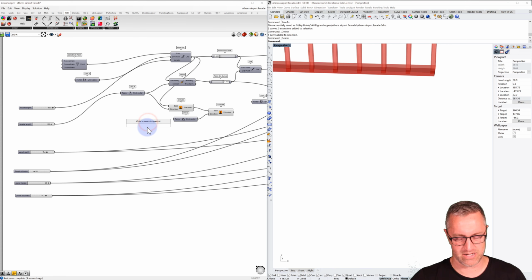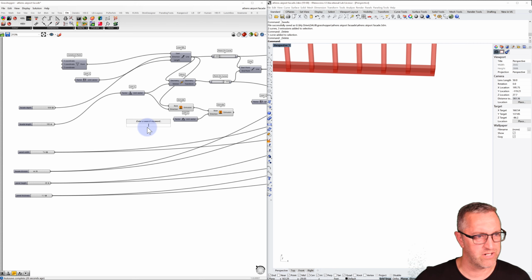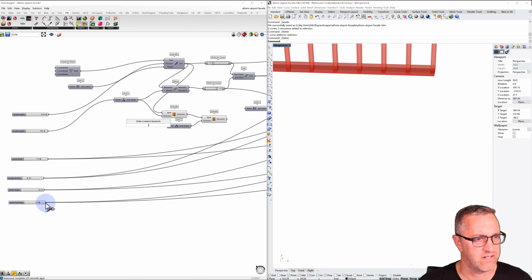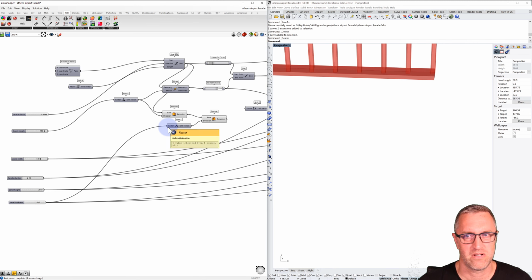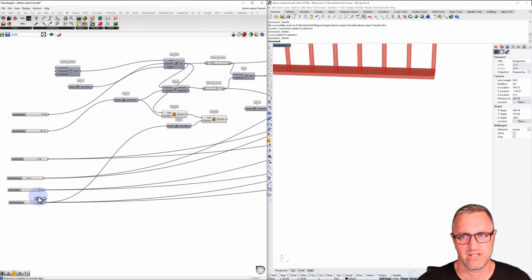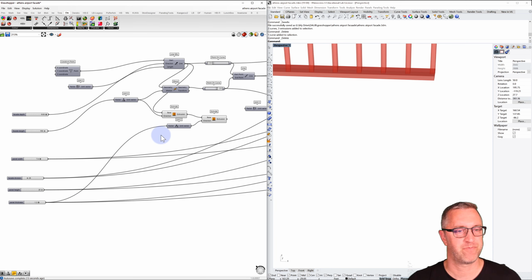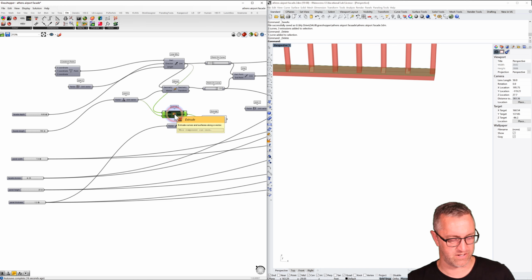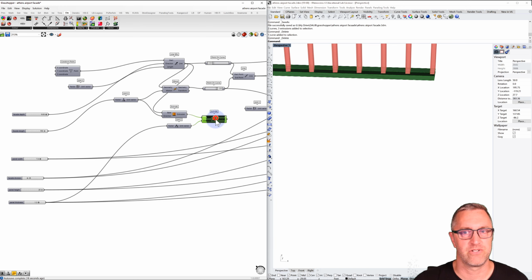So let's make a slider that also, we could use the panel thickness, which is a negative number, and then the thickness of the panel will match the thickness of that piece. That could be a nice thing. If you want those two things to be different, you could give it a different parameter, but I would use a negative number to do that. So let's hide our first extrusion. Now we have that.